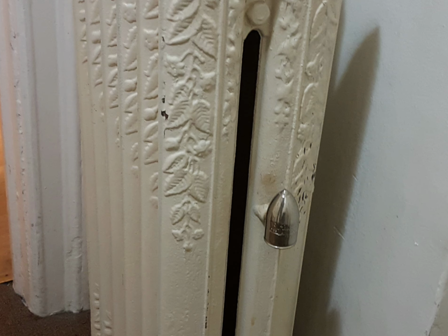And the air vents on the radiators, if those radiators weren't hot, it would continuously keep venting, but not to the point where it sounds ridiculous. It would just vent moderately, and to the point of where the boiler would cut out on pressure. And when the boiler would cut out on pressure, like I said, I had mine set to cut back in at 5 psi. So those vents would essentially stop. Once the pressure started dying down, the vents stopped.